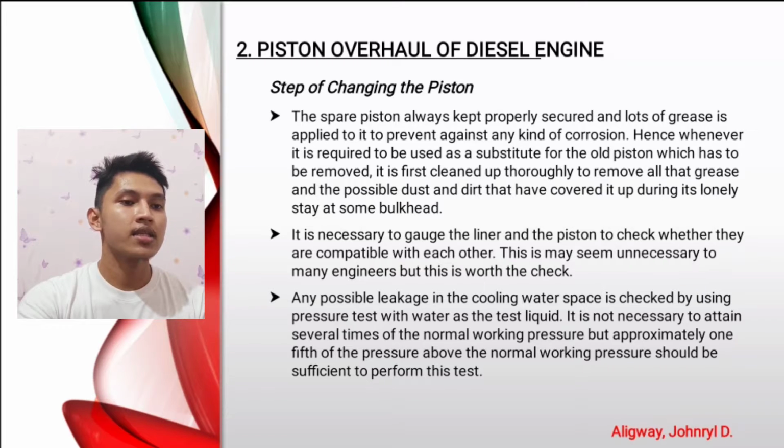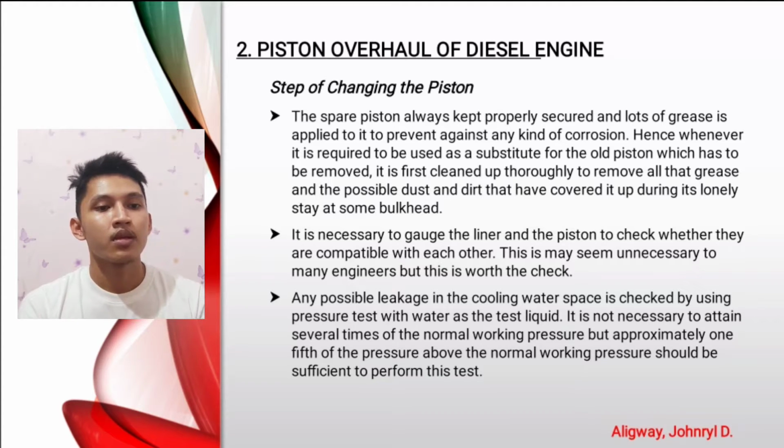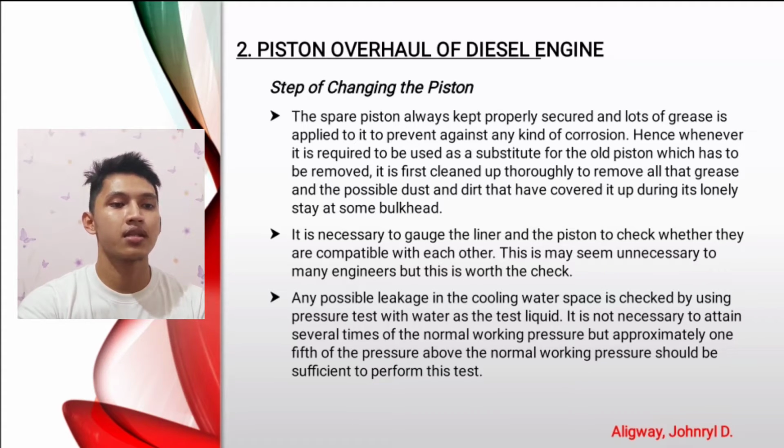Next, it is necessary to gauge the liner and the piston to check whether they are compatible with each other. This may seem unnecessary, but to many engineers it is worth the check. The next step is to check if there is any possible leakage in the cooling water space by using a pressure test with water as the test liquid. It is not necessary to attain several times the normal working pressure, but approximately 1/5 of the pressure above the normal working pressure should be sufficient to perform this test.